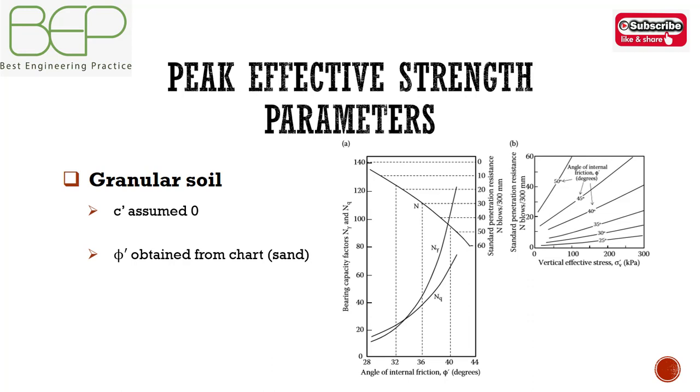Note that these charts were derived from sands, and as noted above, coarser grained soils such as gravel will have an effect on penetration resistance, which may not be completely a reflection of an increased angle of friction.